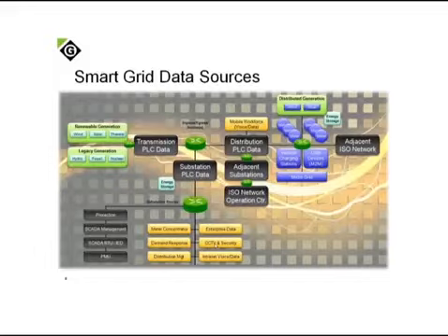So now typically in your substation router, your operational and your non-operational information is completely siloed. Sometimes, depending on the CIP or NERC standards that you're implementing, it could be two completely separate networks, or it's separated by VLANs or MPLS tags. But regardless, your operational and non-operational data is always siloed away from each other and not allowed to intermingle. One is high security, absolutely must-have, high priority information, whereas the non-operational information is typically lower priority and takes a lower class of service.